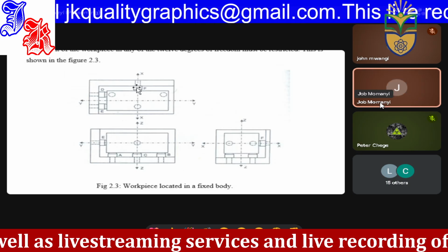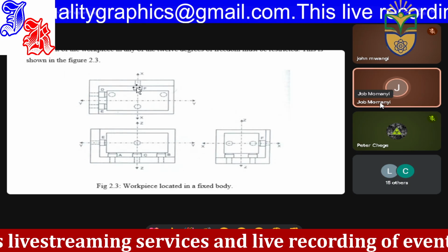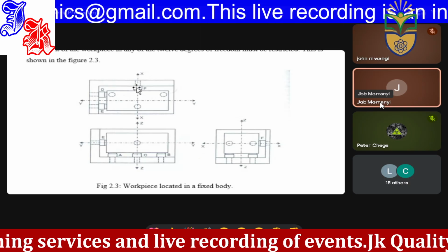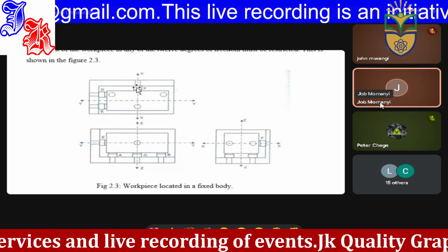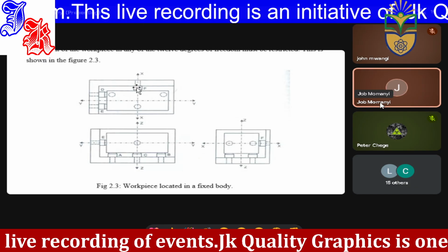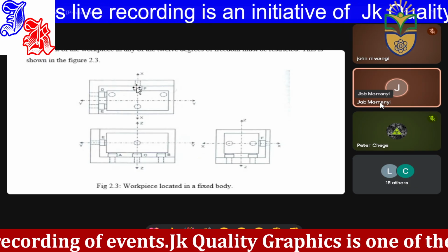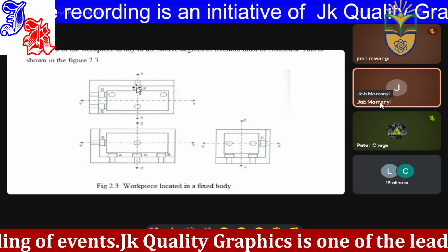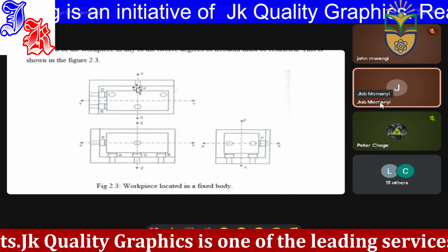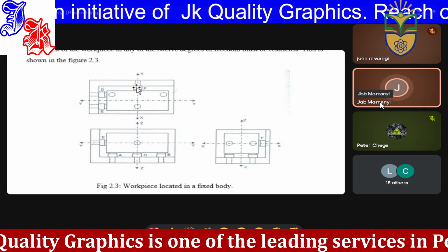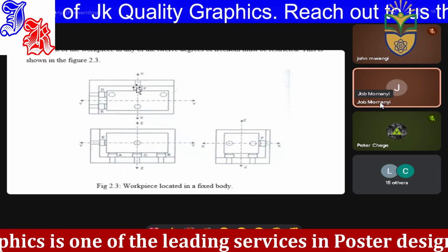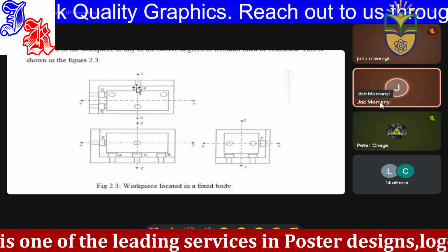So simply we have constrained this workpiece. If we had 6 degrees of freedom from this analysis or from this diagram, I do believe we have arrested all, because you can't rotate this workpiece since it is rectangular and it has been confined from all sides. So you have constricted all kinds of rotation.